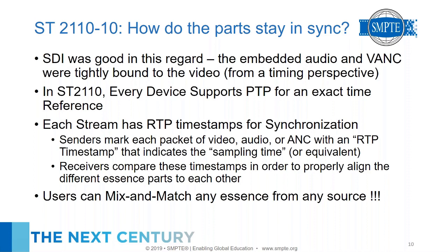The nice part about the 2110 system and having these timestamps is that at least you can measure how late they are. And many devices have an amount of buffering for video and for audio, and so they have a certain capability to match them back up. And that's actually another active topic in the 1-year review, is defining more accurately, or in more detail, how to talk about that, and what does play out delay mean?